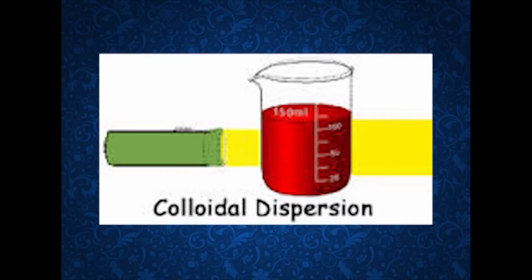The binder is dispersed in a carrier which can be water or an organic solvent, either in molecular form, that is true solutions, or as colloidal dispersions, that is emulsions or sols. Then comes the pigments. Pigments are generally colored inorganic substances that are ground into a fine powder and suspended but not dissolved in the binder. Pigment is actually insoluble in the medium in which it is dispersed. That means the pigment granules remain intact, do not dissolve, and get dispersed across the surface evenly.